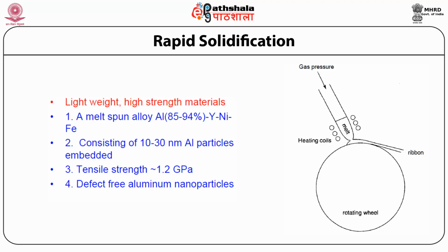Radio frequency heating (RF heating) coils are used to melt a metal, which is then forced through a nozzle to form a liquid stream. This stream is continuously sprayed over the surface of a rotating metal drum under an inert gas atmosphere. The process produces strips or ribbons ranging in thickness from 10 to 100 μm.